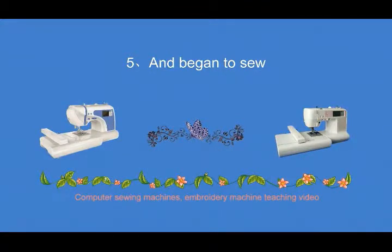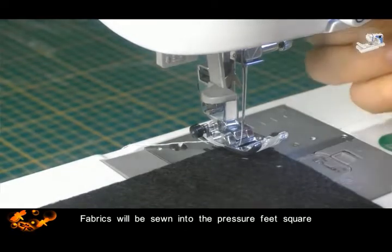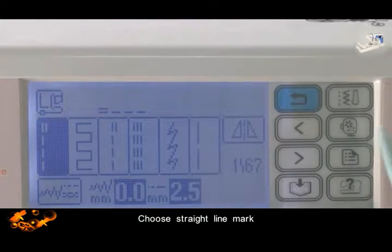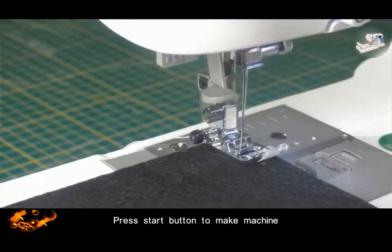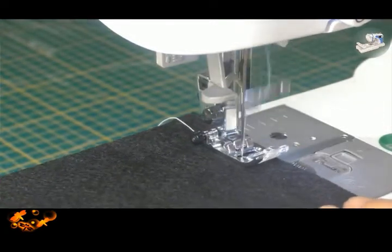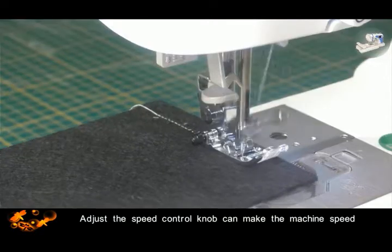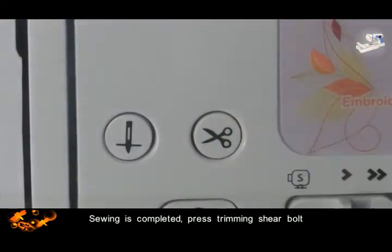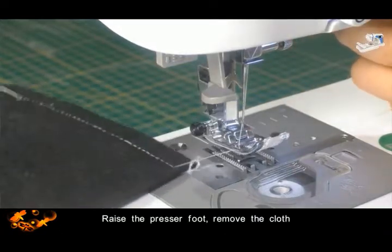5. And begin to sew. Open the power supply. The fabric will be sewn into the presser foot square. Choose the straight line stitch. Press the start button to run the machine. Adjust the speed control knob to change the machine speed. Sewing is completed. Press the trimming shear button. Raise the presser foot. Remove the cloth.